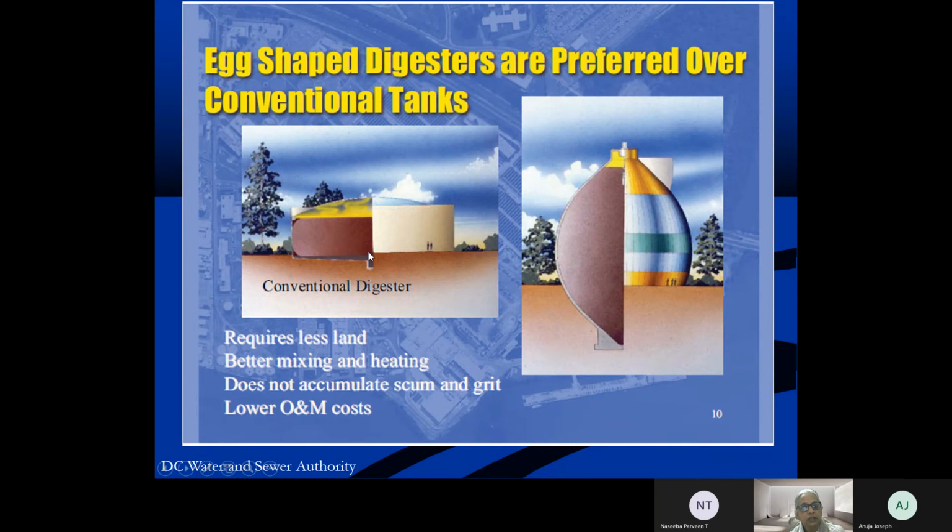So the wastewater sludge would come into the digester, and as the gas is forming, the entire cover would lift to provide equal or constant pressure. So those were called floating anaerobic digesters. They were quite popular in the country at that time. About, I would say, 30 years ago, I've seen a lot of them. And some of them are fixed covers, and the fixed cover means that the pressure builds up over time.